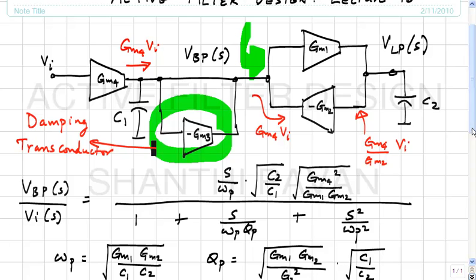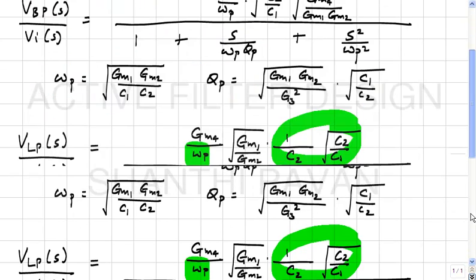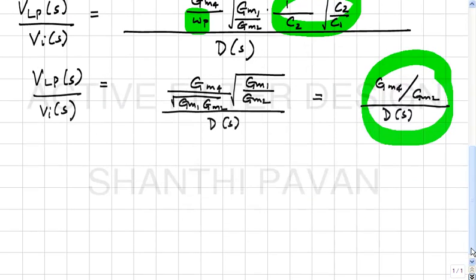All right. So now we have, in other words, figured out how to make a second order section whose numerator is some constant k divided by the standard second order denominator.